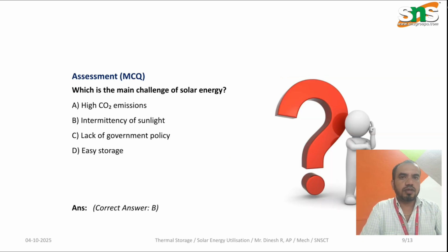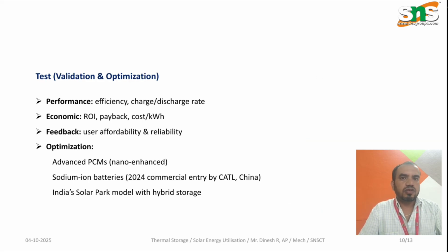A small assessment: what's the main challenge of solar energy? The answer is intermittency of sun, we know that. So how to test the storage? First, we have to test the performance or efficiency, the charge or discharge rate, then the economics, which is ROI and payback cost, and then the feedback, users' affordability and reliability. These are the tests which you have to conduct after designing a solar storage system.